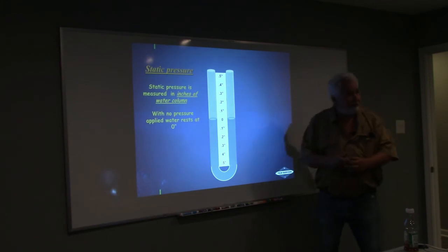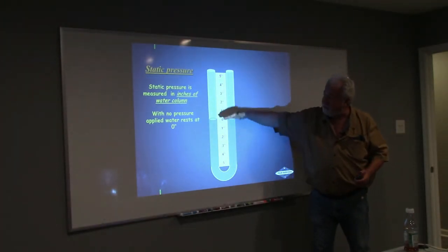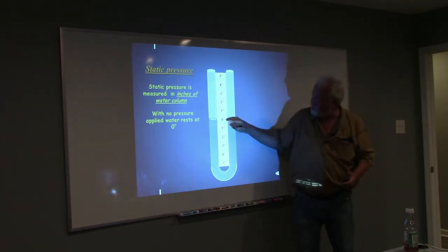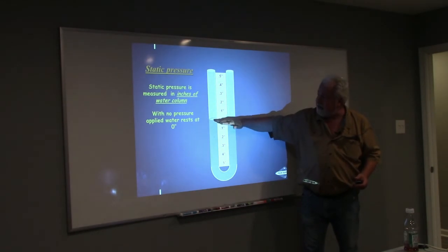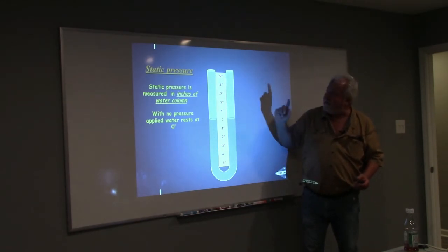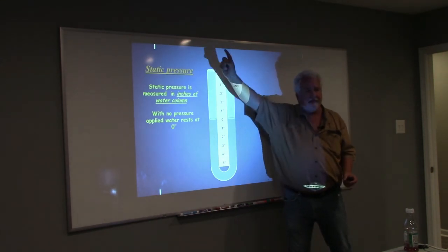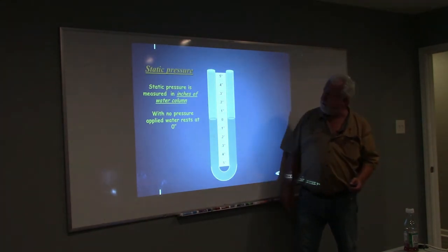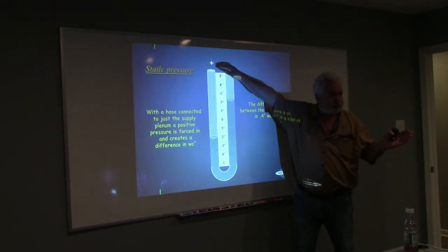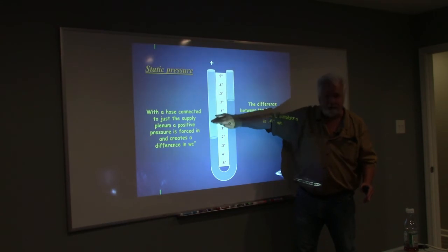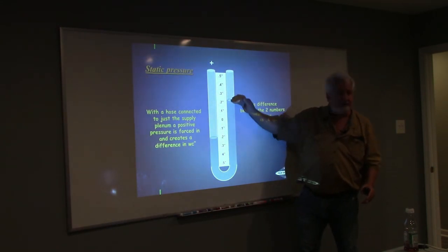This is a U-tube. It was just a clear plastic tube that went around here, and we filled it with water to the 0 level. So right here, I have no static pressure. But if I took a hose and hooked it onto here and stuck it into the supply air plenum, that supply air plenum static is going to push down on that U-tube water, yes? And this side's going to come up.